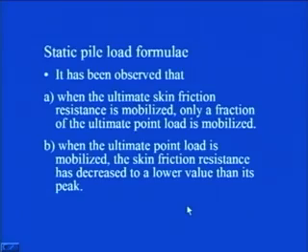See, what is happening in this procedure is that as you are increasing the value of Q coming from the superstructure, a condition occurs where this load Q becomes equal to the ultimate skin friction resistance. There will be a point when the point bearing resistance will be just equal to 0. When you go on increasing the load, what will happen?